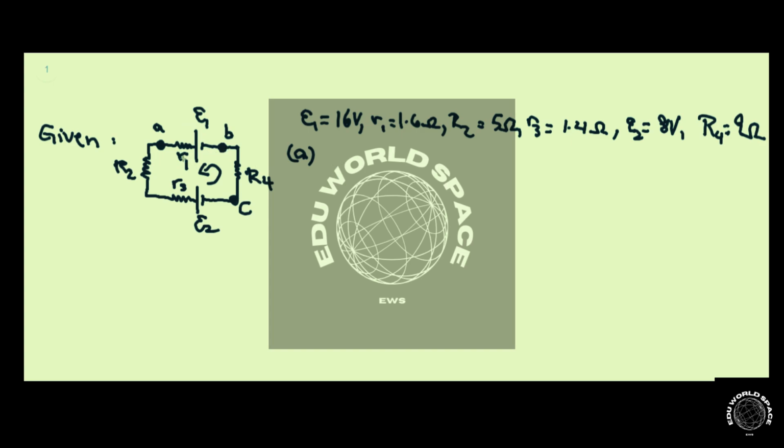So let's start here at the first battery, and then we're just going to make our way around in a counterclockwise direction. So we encounter EMF 1, and then there's R1 with the current I, so there's that voltage drop there. And then another voltage drop of R2I as we go across here.